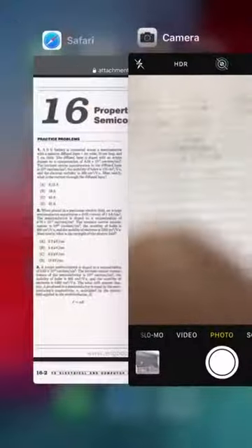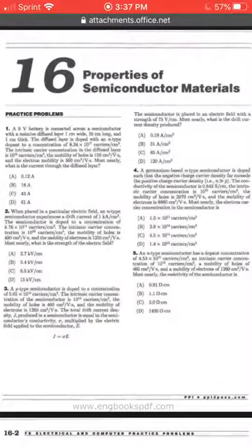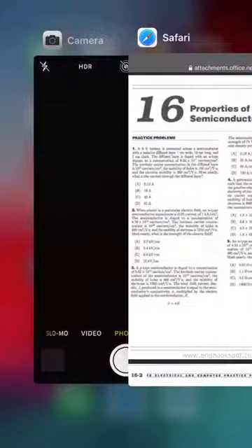So your drift current is going to equal your conductivity times your electric field. But we already have our drift current, so 1000 is going to equal 0.184 E, and E is going to equal about 5.44 kilovolts per centimeter. Now, if we look back at our answers, your answer should be B for number 2. All right?